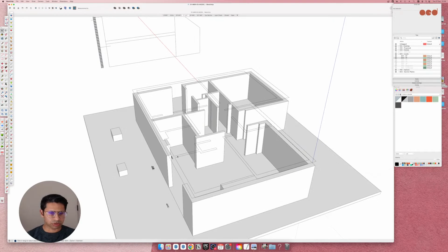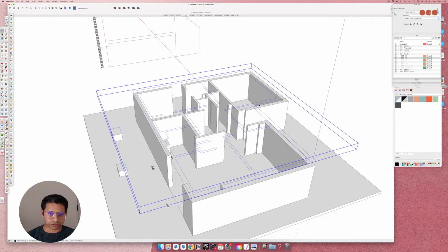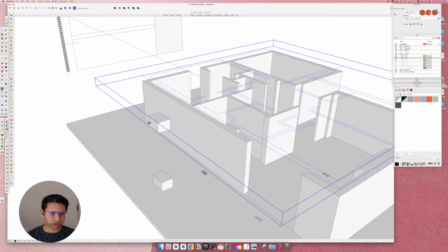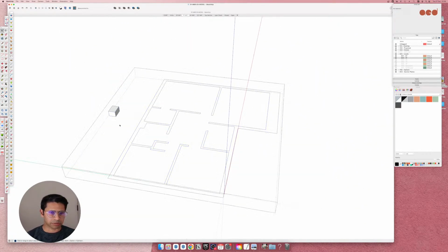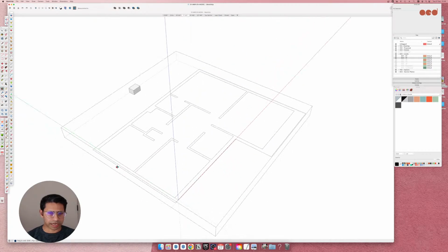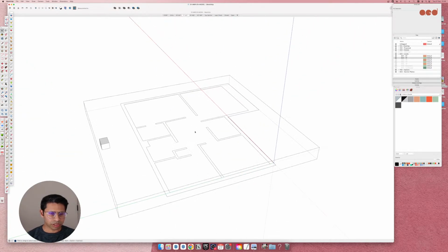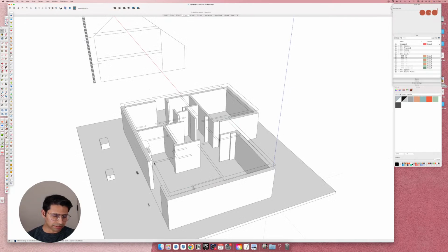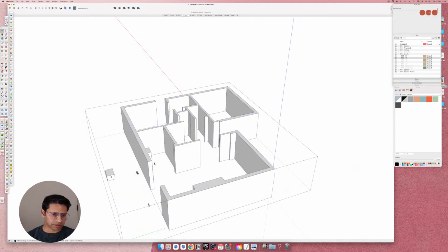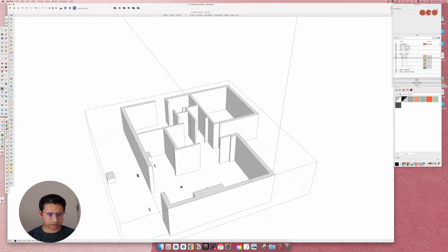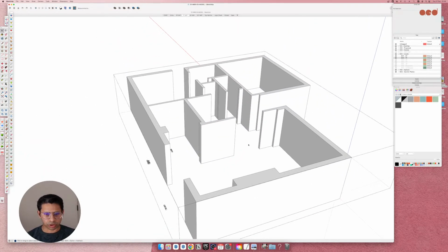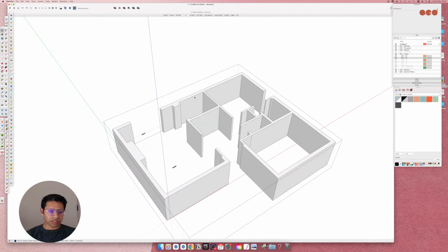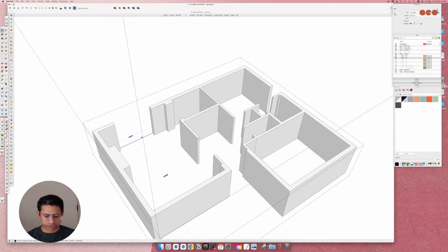That's why, within the group, when it's a 2D drawing, I create a 3D box that helps me go into the group. So I know that if I double click into that, I am looking at the first floor line work, and when I double click there, I know that I'm looking at the ground floor line work. Once I've started extruding, I just delete this box, and it's just a nice thing to have while navigating 2D